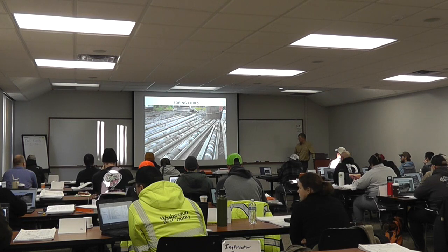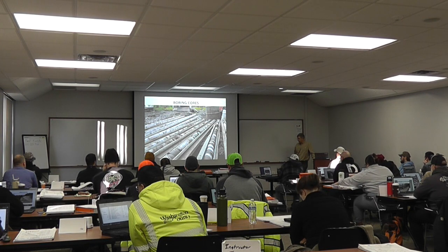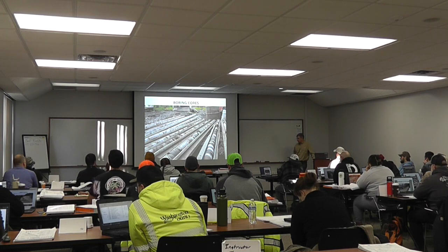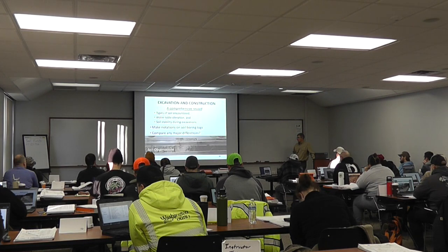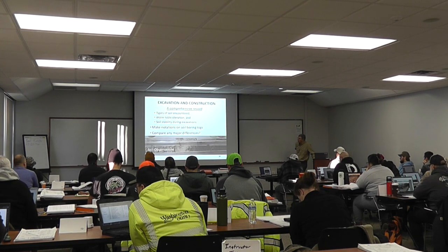So, soil boring cores. When they get in rock, they save the cores like this, and the geotech engineers are able to make a determination of how sound that rock is, what kind of capacity it can hold.